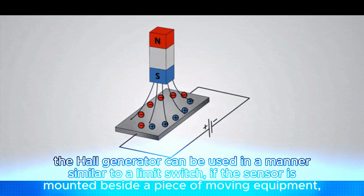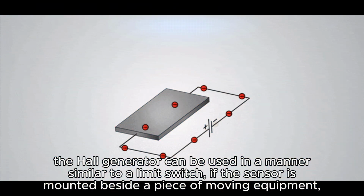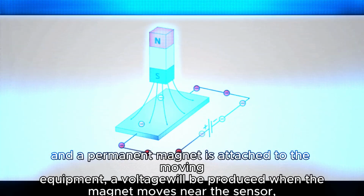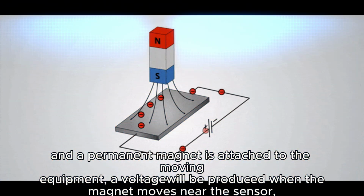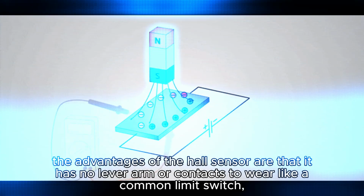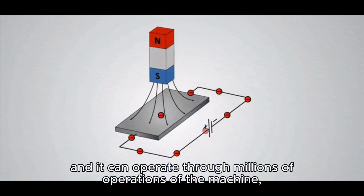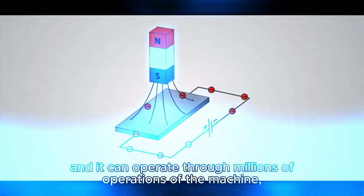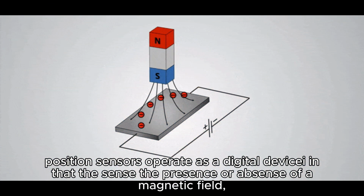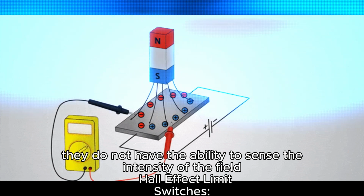Position sensor. The Hall generator can be used in a manner similar to a limit switch. If the sensor is mounted beside a piece of moving equipment and a permanent magnet is attached to the moving equipment, a voltage will be produced when the magnet moves near the sensor. The advantages of the Hall sensor are that it has no lever arm or contacts to wear like a common limit switch, and it can operate through millions of operations of the machine. Position sensors operate as a digital device in that they sense the presence or absence of a magnetic field. They do not have the ability to sense the intensity of the field.